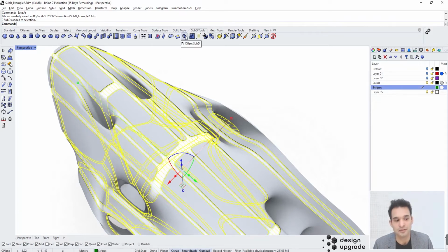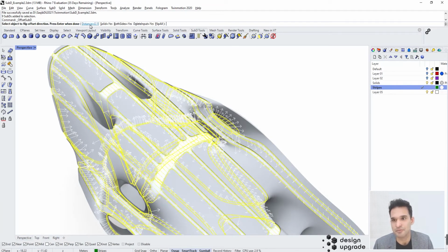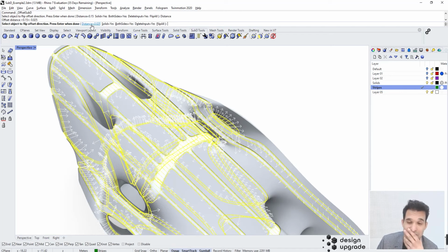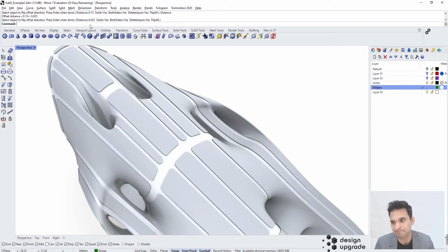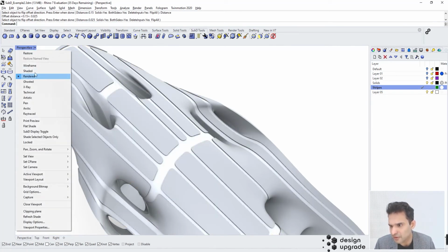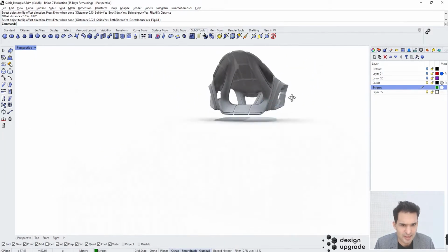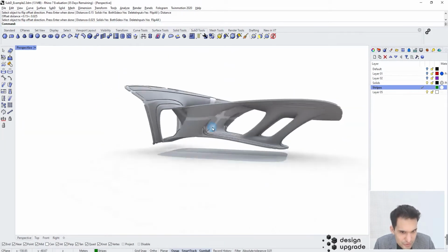So I'm going to use this command here, offset. And this time we want to make it a bit smaller, I would say, so 0.025. So in both directions, that will equal 5 centimeters, which is kind of glass or whatever we define that. If you do that, we should then, if we go to see that it actually works, we have like solid parts, and we have this interesting geometry, I find.